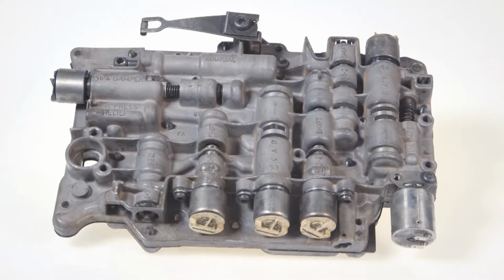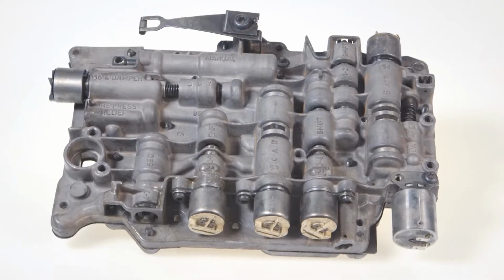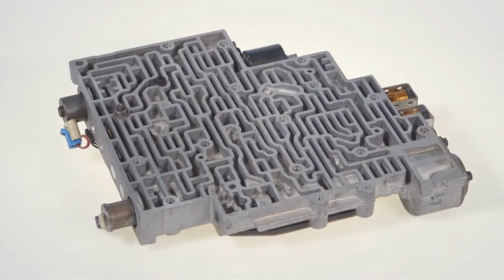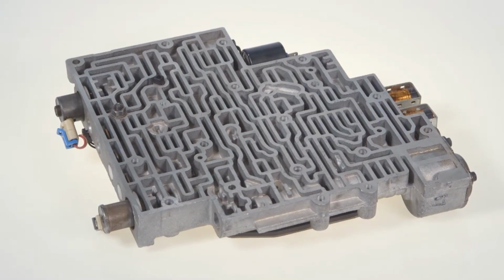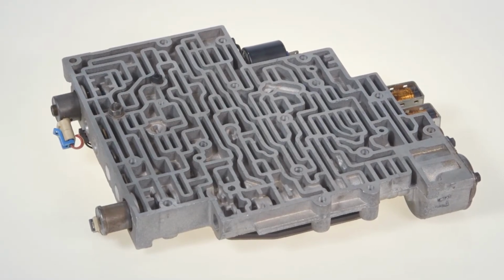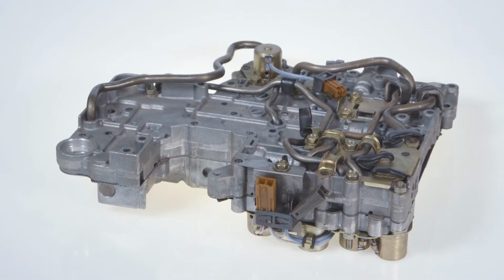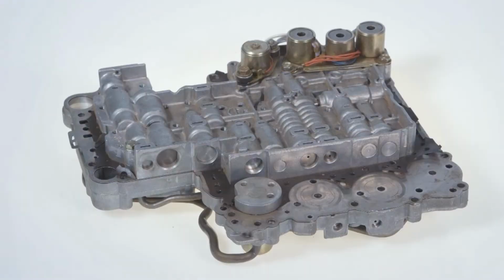In order to understand the principles of hydraulic control, we need a strong knowledge of how an automatic transmission's hydraulic circuitry and valving operates. All automatic transmission systems have a valve body comprising numerous passages and channels which direct the flow of hydraulic fluid throughout the transmission. A special hydraulic fluid is directed through these galleries to different valves in order to activate a clutch or band, which in turn selects the appropriate gear for the current driving conditions.